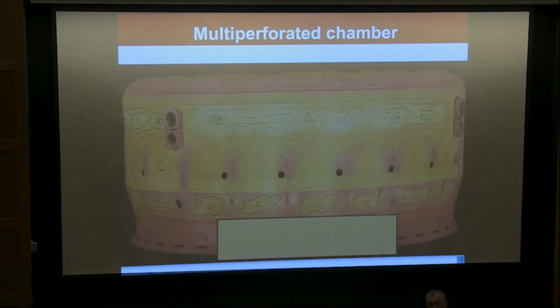And so if you look at a real chamber, this is how it looks. This is a helicopter chamber. Each of these holes here is there to inject a little bit of air. You go through a volcano cloud, for example, in which you have some solid particles. These solid particles melt in the compressor. When they arrive in the chamber, they still melt, and then they enter here, they freeze on the holes, and they block them. Once you have blocked 10 of them, then you get a hole in the chamber. That was one of the reasons why aircraft companies did not want to fly, you know, when you had volcano doing stupid things a few years ago.